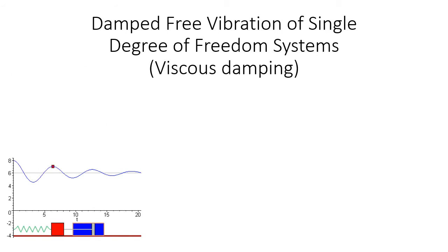So I've got a graphic here which shows the response of a typical damper, for a car suspension for instance. We've got a spring and a mass, but we've now introduced an oil-filled dashpot which acts as a damper, and that absorbs some of the energy that's in the system. It dampens down the amplitude of oscillation, and of course all that energy really goes into generating heat within the damper. And we need to make sure, if we're designing systems, that we get the balance of the spring and the damping right to give us the response that we want.